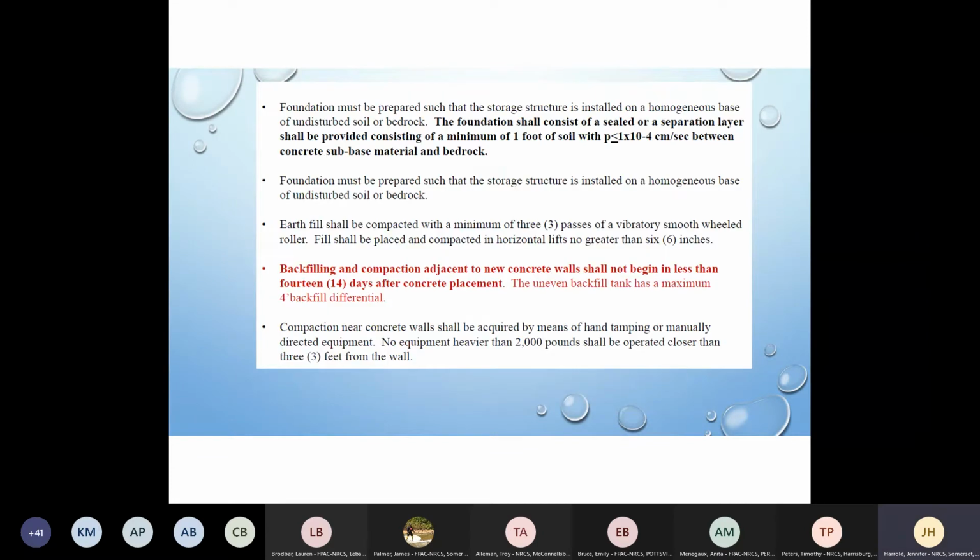So using soil as a construction material, you may have, say, a wetland where you have an embankment, and you may have directions on how many passes with different types of material, or if you have a liquid storage that's HDPE lined, you would have specs on the thickness of the layer, how it is to be compacted. Even if we have just a manure storage in a karst area, we have to have a 1-foot clay liner underneath the storage. And clearly you have to put that in your design to give the contractor an idea of what they need to do and what material we need to bring in, or if it's on site.